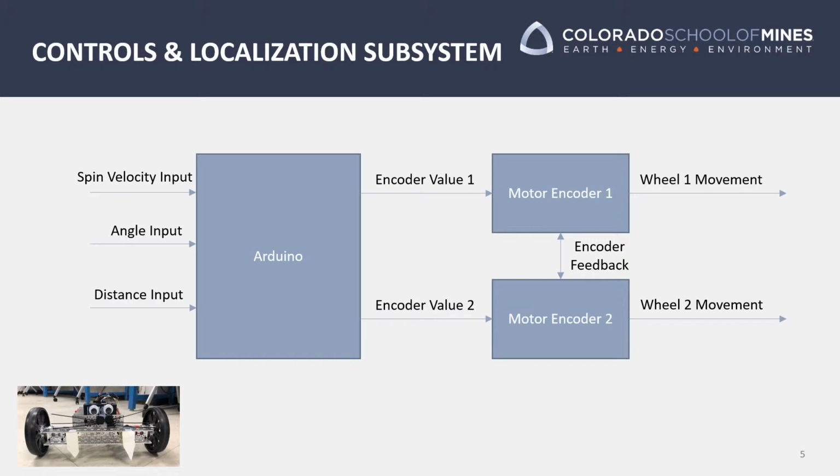The velocity controller used the encoders on the wheels to count the number of encoder counts that had passed in a specified sample rate. It converted this value using the controller to a PWM signal sent to each of the DC motors.